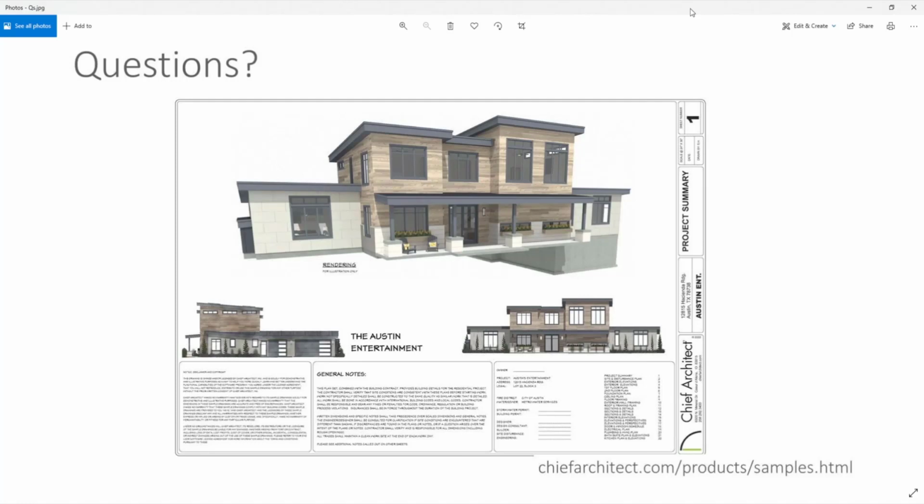So the wall dormer is a dormer where the exterior wall from the floor below goes straight up, cuts through the roof, and say you wanted to make a shed dormer. I don't want the whole area where the eave is to be continuous. I basically want to cut through the roof line and have the wall be continuous from the floor below to create the exterior wall of a shed dormer, which I believe is called a wall dormer. Okay.